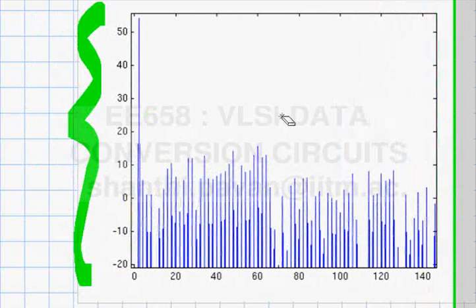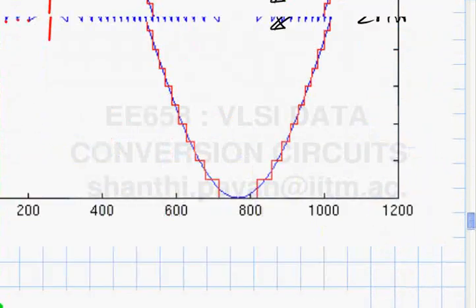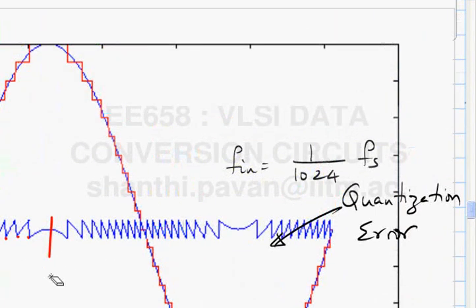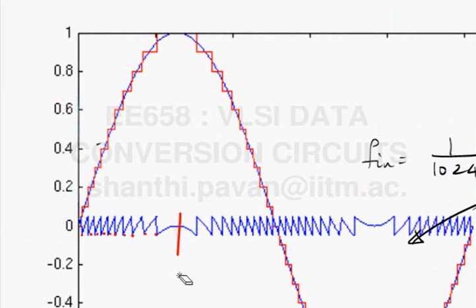So, as you can see, this is around where the peaks are also occurring. Of course, it's not a single peak because the frequency is not uniform. The frequency is changing. So, what does that remind you of? Where have you seen in your earlier classes something where the frequency is not constant but varying? In your basic core courses, have you seen something where the amplitude is constant and the zero crossings are changing? Frequency modulation.